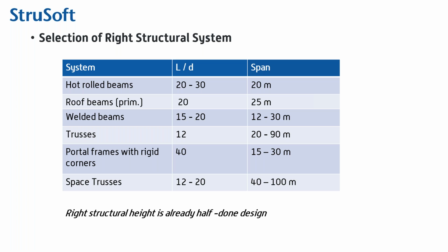And the roof beams, it's about the same. And if you go to the trusses, you should usually consider something like this. If the span is 12 meters, your height should be 1.2 meters or 1 meter. And if you leave it like that, usually your design is really conservative. The internal forces of your elements do not grow really high, and the design of connections is easy.